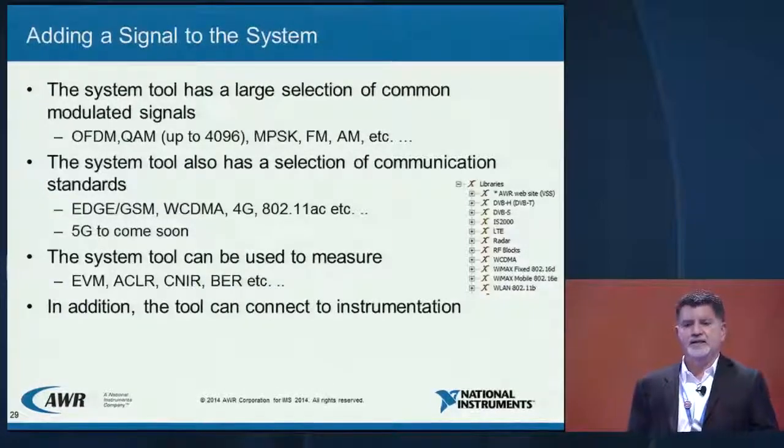Now we move on to the next step. I make all my qualifications for spur analysis. My noise figure analysis is done. I could utilize VSS signals to stimulate the same link. And at this point, the metric is going to be different. The metric that we're going to be looking at is bit error rate.